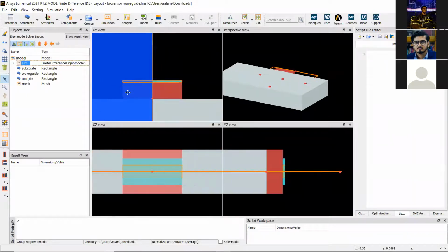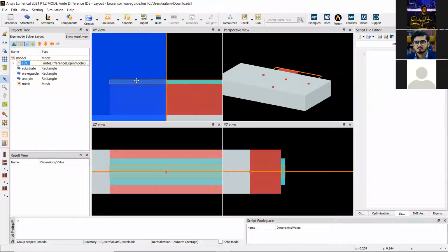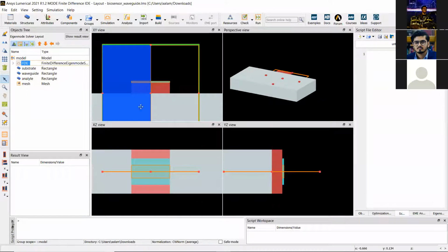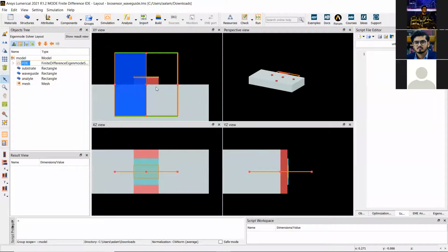And then you run another simulation where you assume that the analyte has interacted with some biomolecule, so its property has changed. Then you can see the effect of the change in the behavior of this layer on the optical property of your waveguide. So that way you can run, say, 2 different simulations and see how your circuit behaves, given that there is some biomolecule present in the environment or not. And that, in my understanding, is one example of how you would simulate a biosensor.